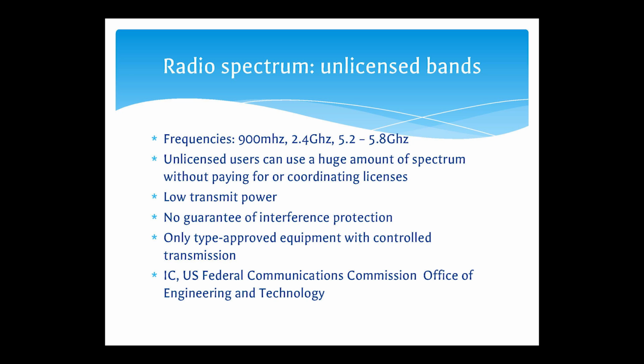These tests usually include that the equipment does not easily allow transmission above the standard maximum transmit power that should be allowed in licensed bands. And also, these tests verify that the equipment does not have spurious emissions. So to make sure that your 2.4 gigahertz Wi-Fi router, if it has an 800 megahertz CPU, hasn't been designed without filters to save money, and then starts transmitting at 800 megahertz and screwing up your cell phone at 850 megahertz. That kind of idea.